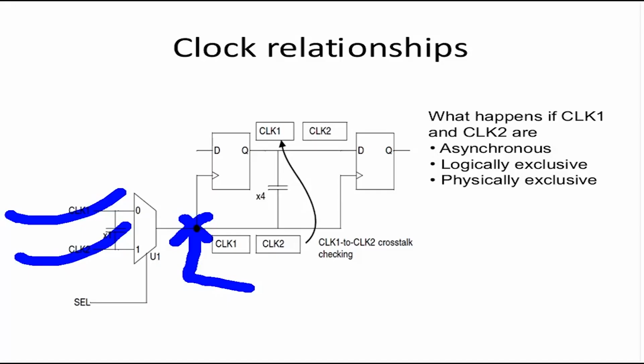What it will tell PrimeTime is that it will never launch on one clock and capture on another clock in terms of crosstalk. So the timing windows again will not be infinite. There will not be any crosstalk effect which is special to the two clocks being different, right? They are physically exclusive. They cannot exist together, right?